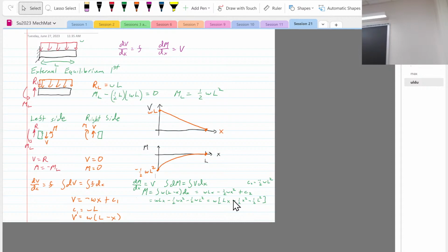So, can a bending moment apply? A bending moment is going to give you no shear stress, just sigma. It's true though that you can have a shear force in bending, due to the shear force, which is related, when we do the derivation, to the bending moment. But for a bending moment, you're going to get a normal stress, a bending stress. For a shear force, you have multiple ways that you get it.